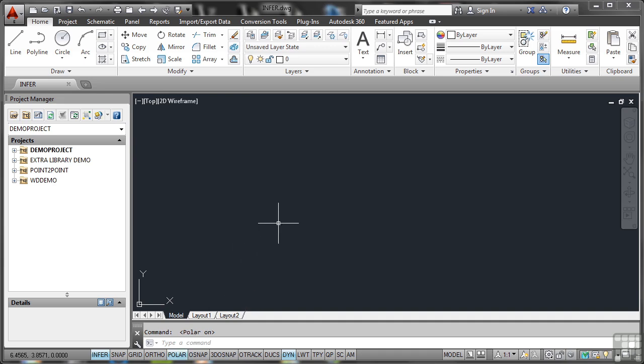Into the drawing area, you'll also notice that DYN, Dynamic, is on in the drafting settings. That's Dynamic Input. I never ever turn Dynamic Input off. You'll see why when we go into Dynamic Input later when we discuss more of the drafting settings.